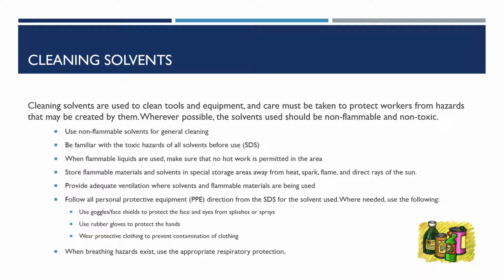Cleaning solvents. Cleaning solvents are used to clean tools and equipment, and care must be taken to protect workers from hazards that may be created by them. Wherever possible, the solvents used should be non-flammable and non-toxic. Use non-flammable solvents for general cleaning. Be familiar with the toxic hazards of all solvents before use. When flammable liquids are used, make sure that no hot work is permitted in the area.